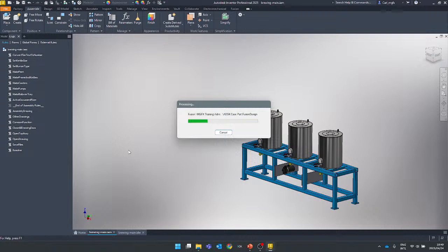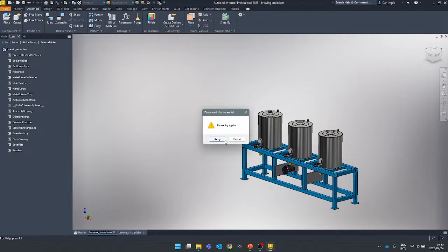It is not something that you would be able to edit inside of, let's say, Inventor. If you open a Fusion part, or if you're in Fusion and you open an Inventor part, you would not edit that part in Fusion. You would just use it there so that it's in the assembly. Okay, I see I've got a bit of an error there. If you need to make changes to that component, you would then change it in Inventor and Fusion will update to show that change.